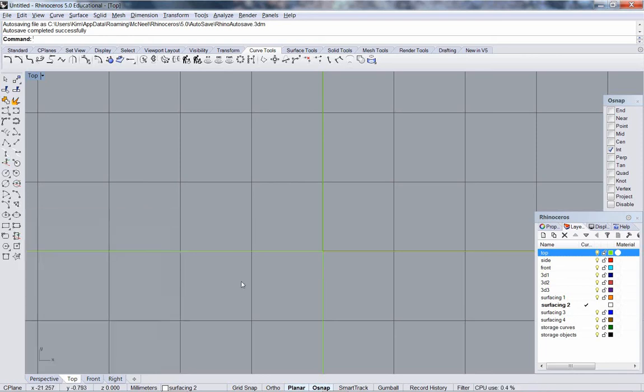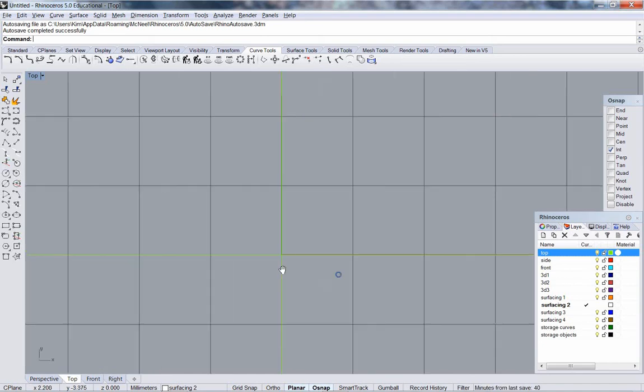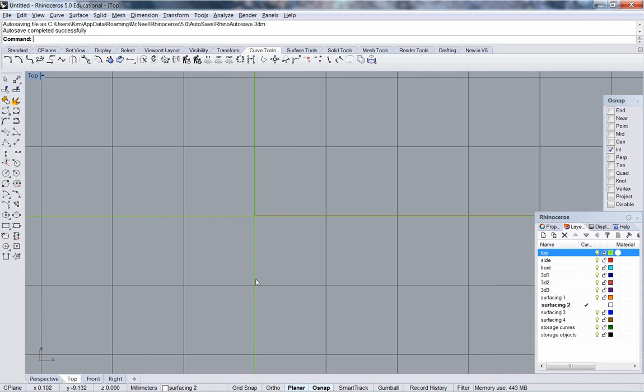This tutorial is for drafting. We're going to be drafting, JD 139, an eternity band. The eternity band will be 2 millimeters thick. It will have 3 millimeter stones going all the way around, and 1 millimeter rims on either side of the channel set stones.